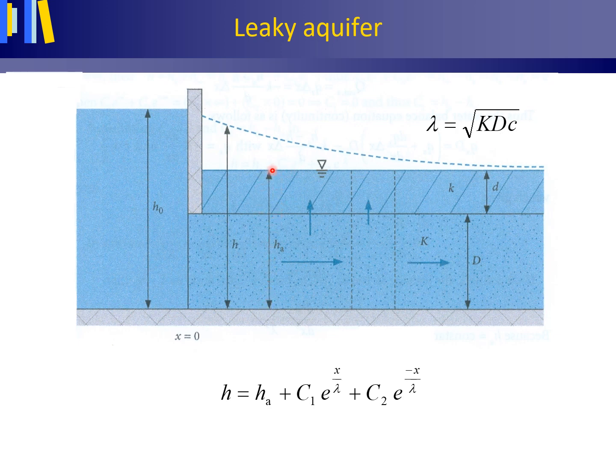In reality, this HA would lie slightly below the land surface, but here, simply for ease of calculation, HA has been set at the land surface. As a reference level, a hydraulic head of 0, we will use the top of the underlying impermeable base. The dike in the cross-section is simplified to an impermeable vertical screen above the leaky aquifer.